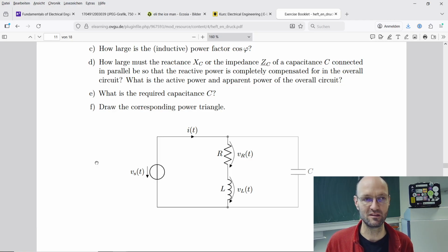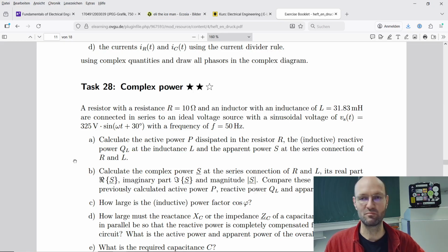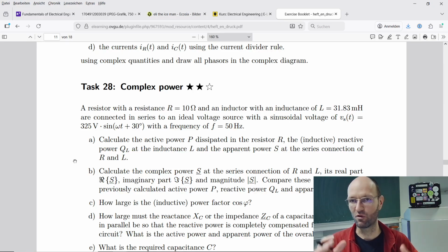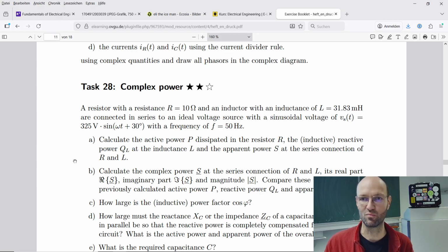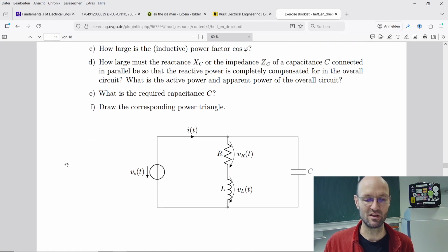So the capacitor needs to be able to handle the 325 volts plus some, because in the mains power grid you might have overvoltages due to surges and bursts and lightning strikes to the power grid and switching events with motors and so on.